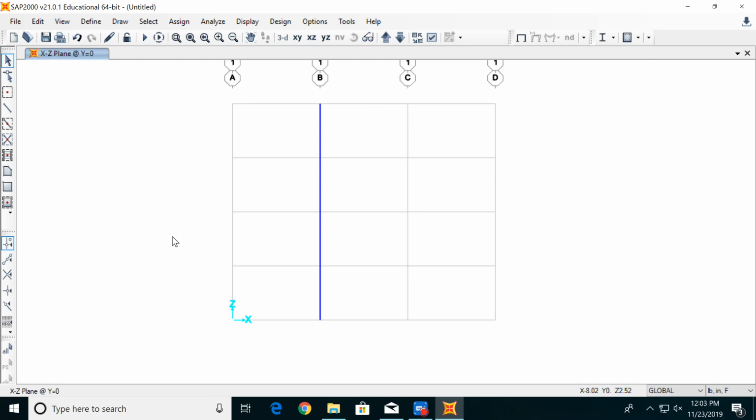From there, we are going to be placing a fixed end on the bottom to represent the acrylic piece being attached to a table or some other fixed end. And we're going to keep the free end on the top. So we're going to highlight that bottom grid point. Please make sure to only select this grid point. You can see that when it's selected on SAP, a little yellow X will come up. If for any reason you selected multiple, just hit the Escape button and then do it again.